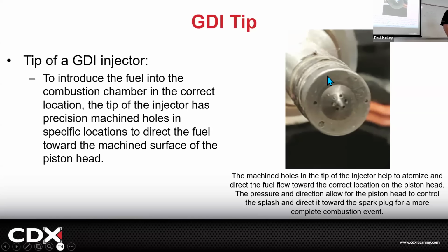Now, once in a while, you can do one injector and have it be no issue, but I would at a minimum let the customer know, hey, you've got a bad injector. We'll put one brand new injector in, but if your other 3 injectors are starting to be restricted, you may get an imbalance issue, in which case you'll have to do all of them. Do you want to do them all right now? And that's kind of where I sold that guy on the V8, that Silverado. I said, I'll put one injector in, no problem. But if you get any imbalance codes, the next bill is on you. I'm no assistance, no help to you. Like, now's your chance, no minimum 1 hour extra labor for me to do all of them. And it's kind of like, yeah, all right, do them all. No problems. That was a couple of years ago. And he's been really good, right?